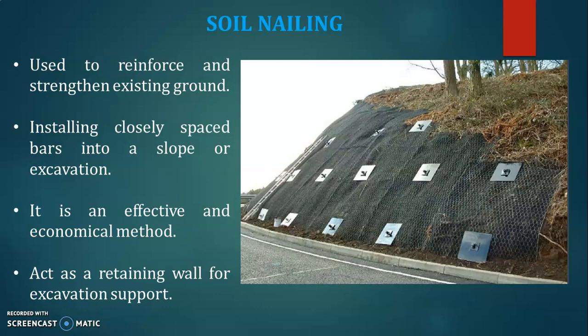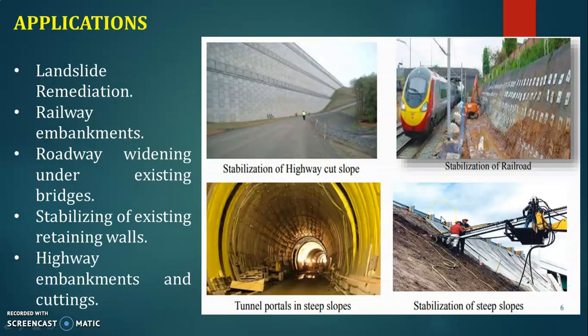It is used to reinforce and strengthen existing ground, by installing closely spaced bars into a slope or excavation. You can see here these are the soil nails. It is an effective and economical method, and acts as a retaining wall for excavation support.